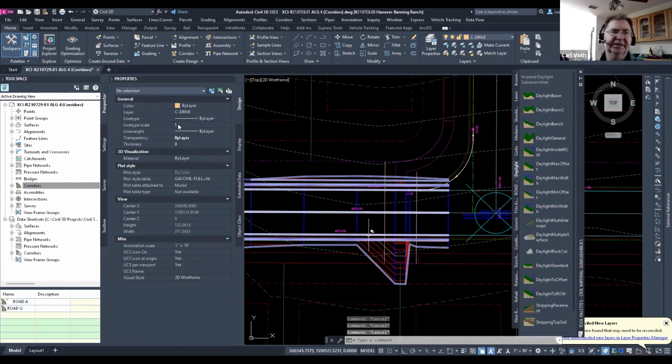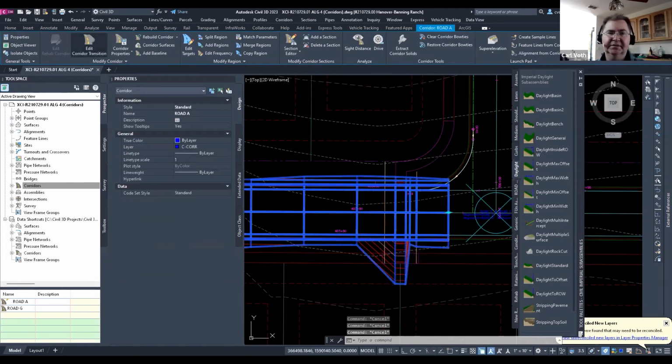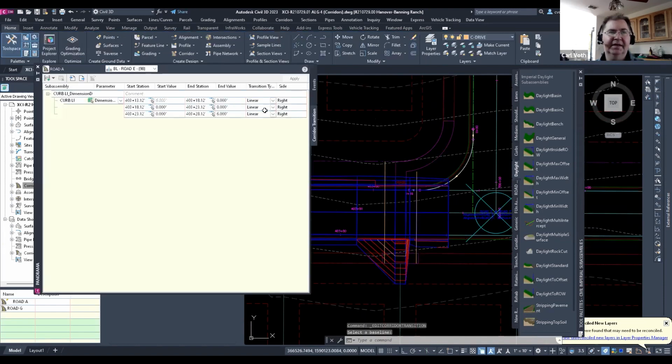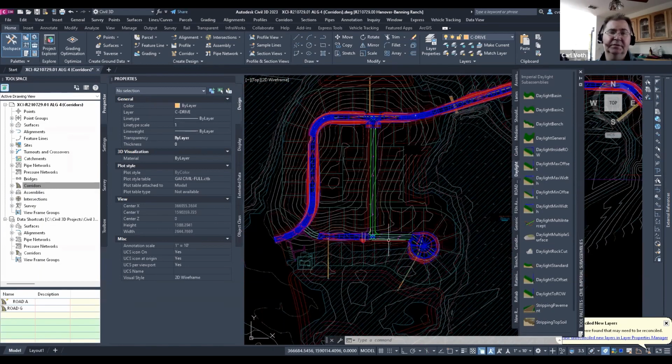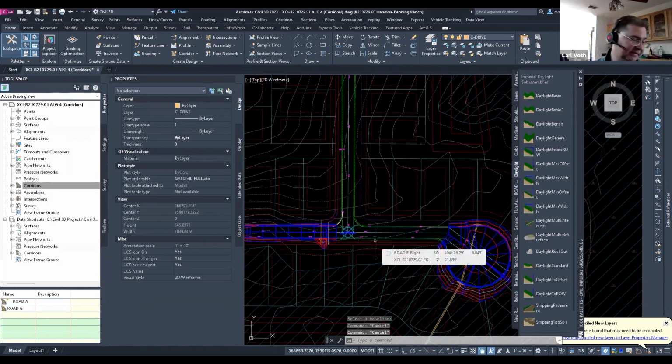And then also, if we need to, we can come back and change that editing transition tool and modify these going through. It stores this information, and we can add additional new transition sets to that region section. And also we have whether or not we want to do bay tapers or reverse parabolics for those transitional types, and then also what side we want that to take care of. This also works with lanes with daylighting options as well. So the possibilities are endless through there.